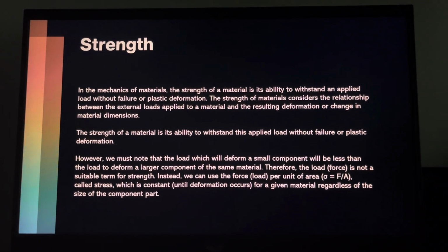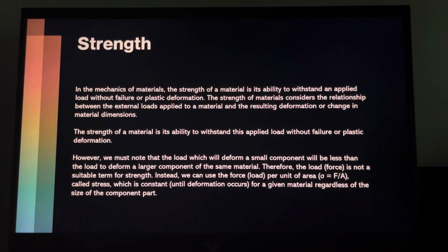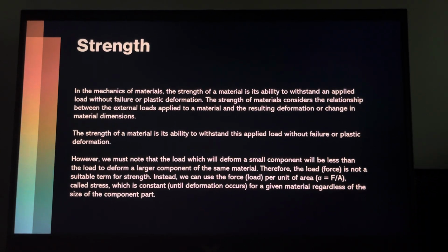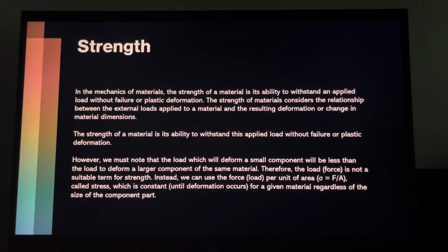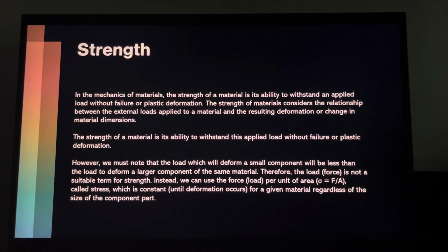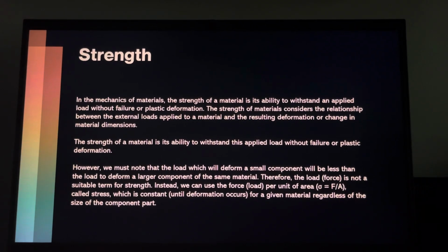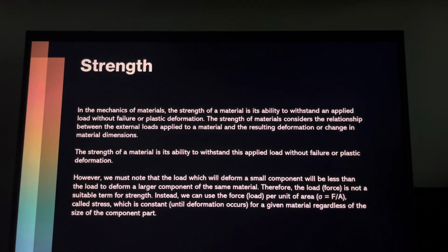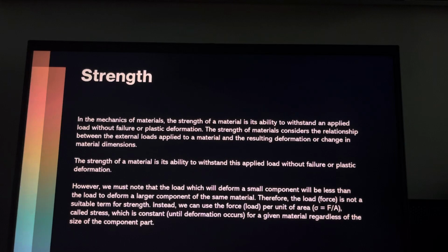Instead, we can use the force per unit of area, called stress, which is constant until deformation occurs for a given material, regardless of the size of the component part. So in this concept, strain is also a very important variable since it defines the deformation of an object. In summary, the mechanical behavior of solids is usually defined by quantitative stress-strain relations.